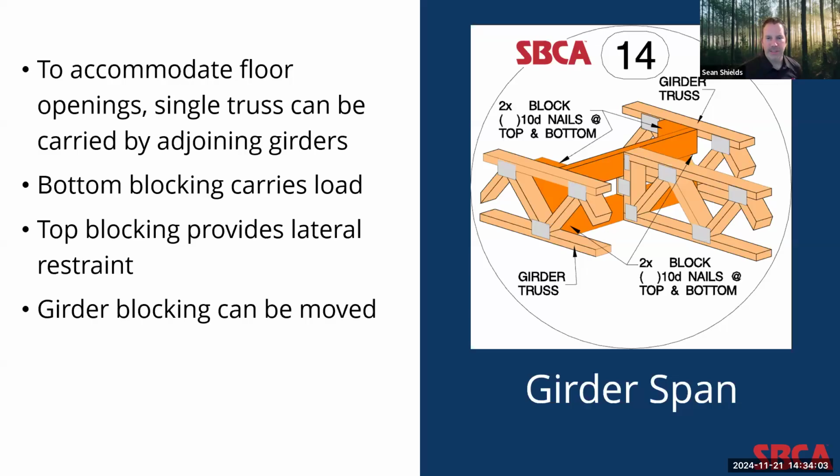One thing to note about this detail is that typically the blocking affixed to the girder trusses, in this detail, is located on the other side of the carried truss. But if you wanted a cleaner opening in the floor, that blocking can easily be moved to the other side of the girder trusses.